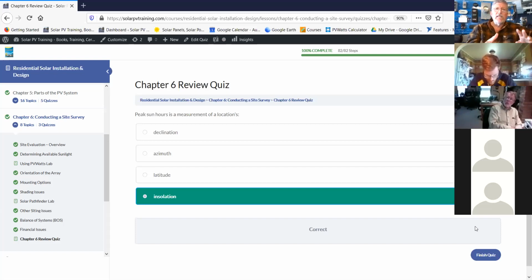So when you look up on PV Watts and it says that in Central Ohio, you have 4.32 hours of insolation, they're not saying that the sun only shines for 4.32 hours and the rest it's darkness. They're saying that over the course of the day, you have 4,320 watt hours of irradiance hitting a square meter section of land. In the early morning, it's going to be less and diffused. Noon, it's going to be stronger. Evening, it's going to be less. But when you take it all and measure it all together on average, it's going to be 4.32 hours of 1,000 watt per square meter sunlight. And that's going to be very helpful when we're doing our calculations to figure out what size array we need.